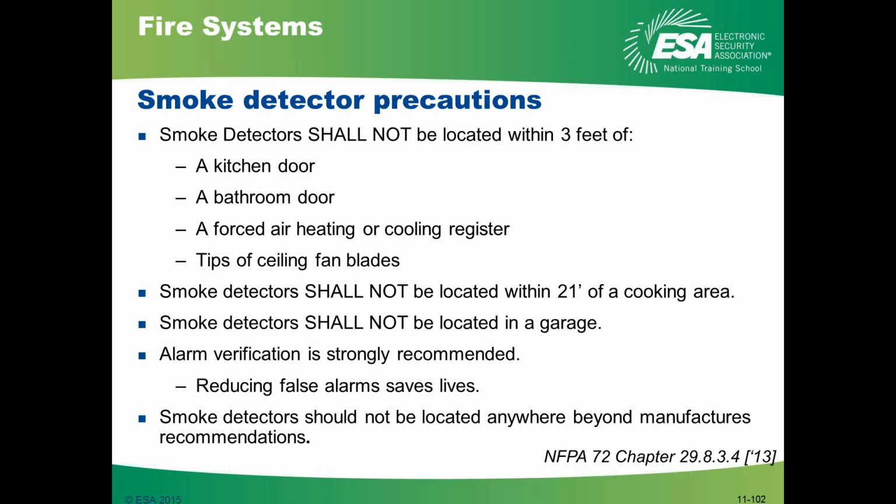Smoke alarms and smoke detectors used in household fire alarm systems installed between 6 feet and 20 feet shall be listed for resistance to common nuisance sources from cooking. So there's just been a change in that area that you may want to, as instructors, become familiar with.